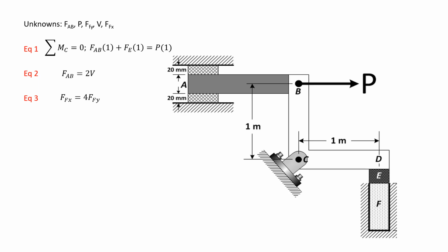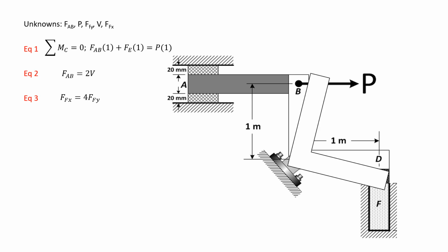So this is the figure. Of course, remember that BCD is rigid as well as E. So they will move, BCD and E will move, but they will not deform. So how will BCD move? Here. Of course, P is pulling point B to the right. Hence, your BCD, your linked BCD will rotate. Okay? Will rotate clockwise.